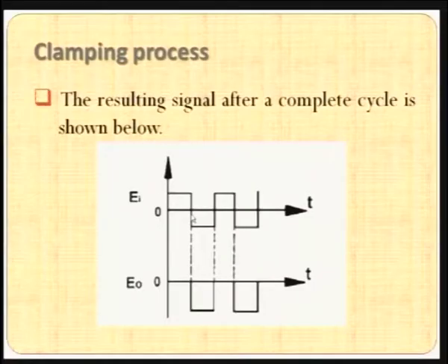So, it is an RC combination, and because of that the charging happens, and after that the instantaneous voltage is taken as a negative value when the negative cycle appears across the input, and thus the voltage is clamped, it is shifted. Why are the RC values very small here? Because the quick discharging should happen.